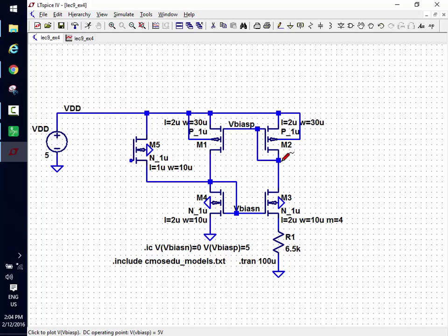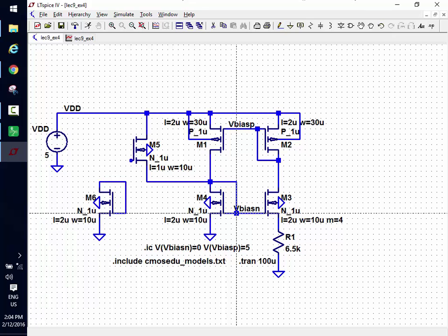Does everybody follow that? But once the circuit snaps, I want this to shut off and go to ground. The only way I can do that is if once the circuit snaps, this gets pulled to ground. So what I'm going to do is put a current mirror right here that mirrors the current that flows.